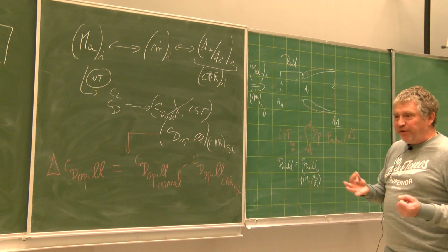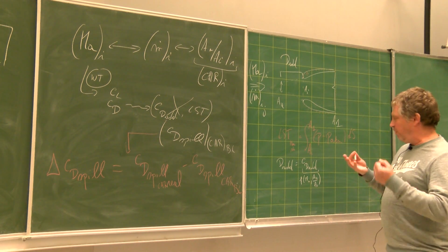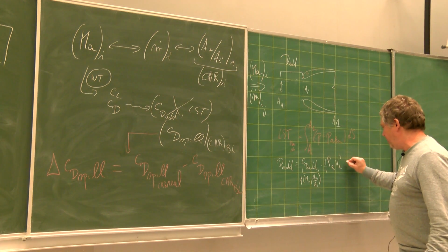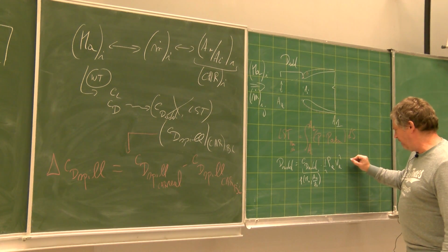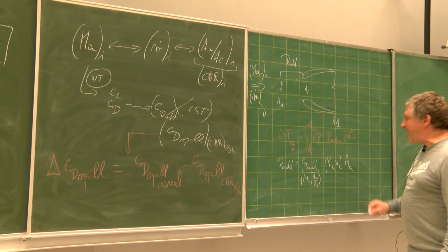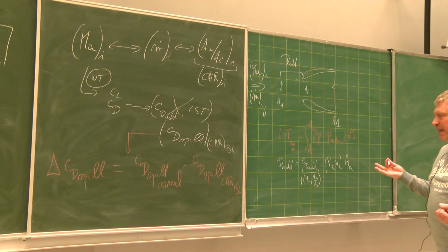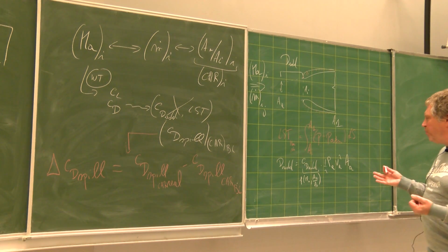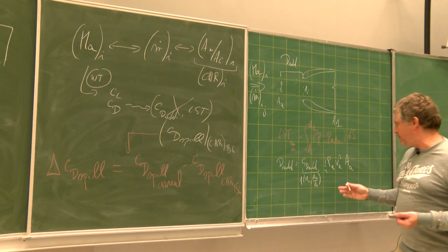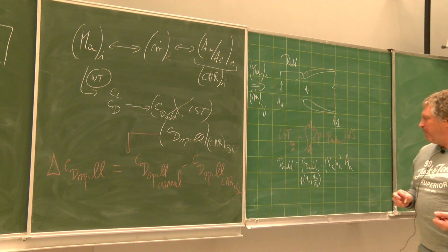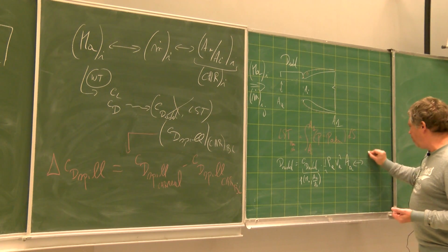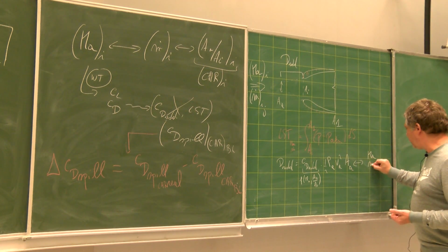So this is a given table or equation or figure, multiplied by 1/2 rho A VA squared, multiplied by the surface, which is the section AA. It's quite easy because when you know the mass flow rate, you know AA, you have VA related with MA, 1/2 rho A multiplied by this factor coming from this figure. And you do that also for different Mach numbers and different m dot.